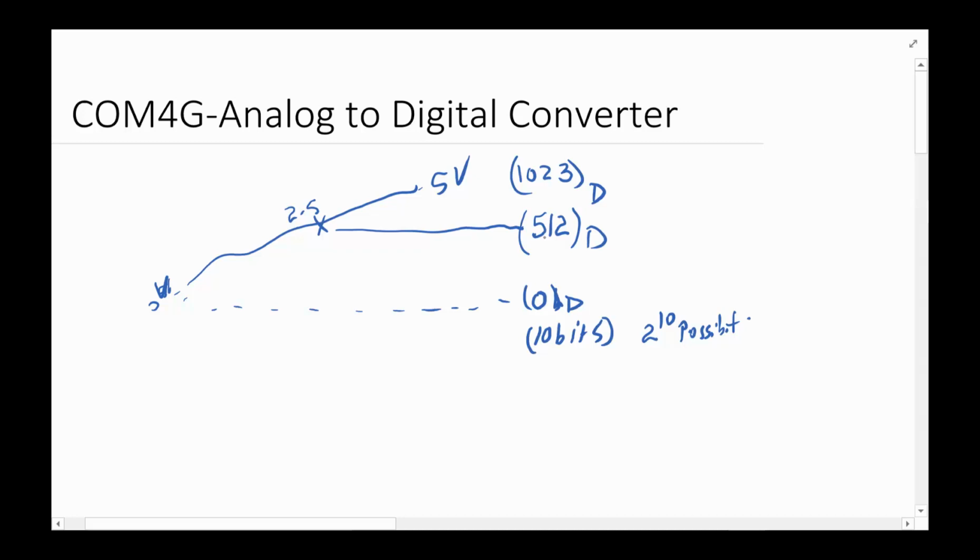So that's basically an A to D conversion, an ability to take a range of voltages from 0 to 5 and give it a number. You might ask, why are we doing this? The reason is that practically everything in nature that the computer needs to sense has first to be translated to voltage, whether it's light, distance, the gravitational force of a star far in the distance, your DNA structure being analyzed, or a chemical property.